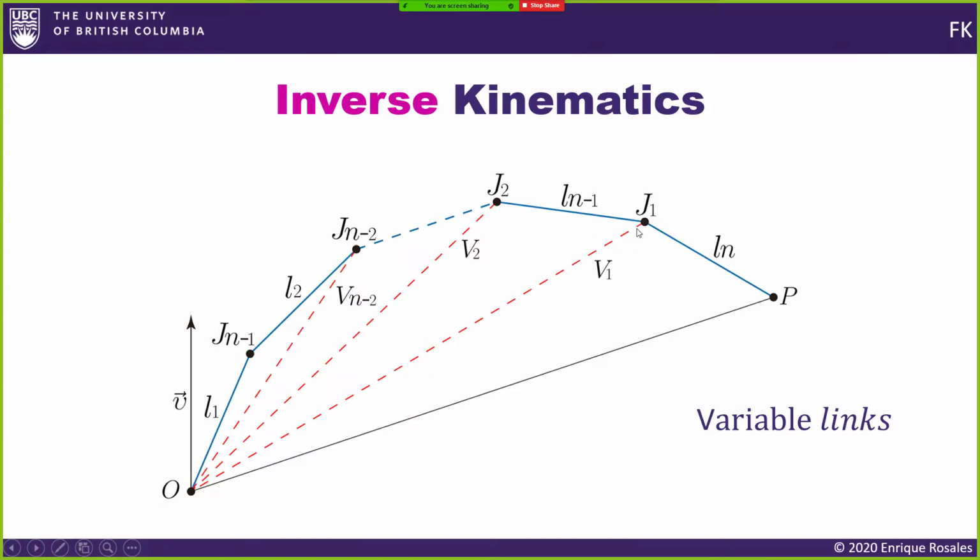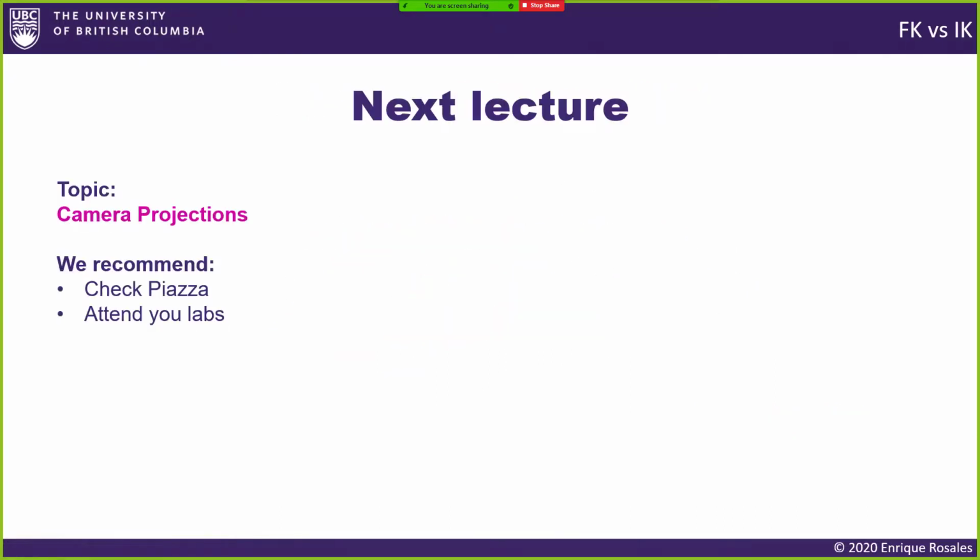And basically your solution for the first inverse kinematic problem becomes the end effector for the next one. And then you compute this inverse kinematic problem, and that solution becomes the end effector for the next one and the next one, and basically you go backward, right? And with that, if you compute everything there, you end up, give me a second,